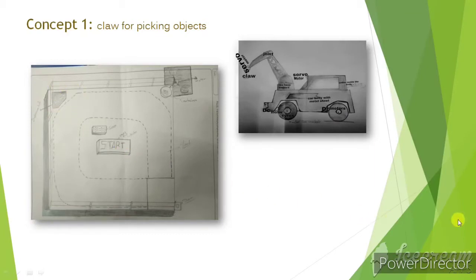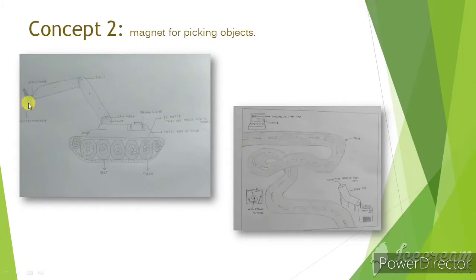Coming to the first concept, the claw with dent is attached to the robotic arm for fetching the gift from the containers. On the board, there are 3 containers which are connected to each other and rotate at a set speed so that the probability of hitting the object decreases. The indicators are placed in the central empty space and the run track is loop type. And further, in the second concept, there is an electromagnet fixed to the robotic arm. We can attach a small metal piece on the gift wrappers which get kept in the containers. On the board, the track is a curved path, and the start and the end point are on different, opposite sides of the board.